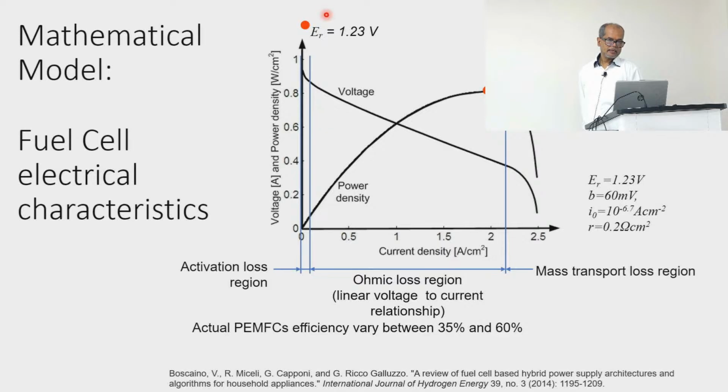And then at different points, if you multiply voltage and current, your power curve will be like this, right? And then you're going to find at what point you get the maximum power. And then your MPPT control, again, for MPPT there are different algorithms that you can use to find out exactly the maximum power point.